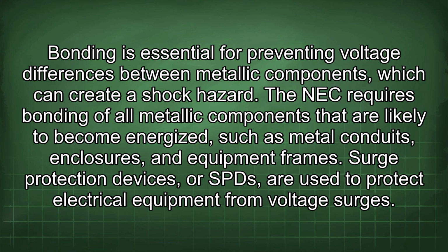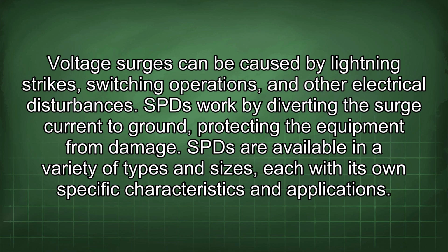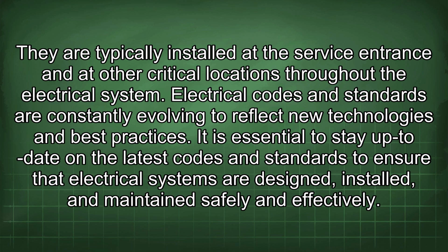Surge protection devices, or SPDs, are used to protect electrical equipment from voltage surges. Voltage surges can be caused by lightning strikes, switching operations, and other electrical disturbances. SPDs work by diverting the surge current to ground, protecting the equipment from damage. SPDs are available in a variety of types and sizes, each with its own specific characteristics and applications. They are typically installed at the service entrance and at other critical locations throughout the electrical system.